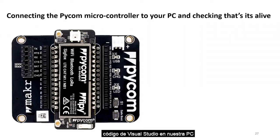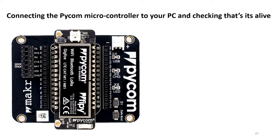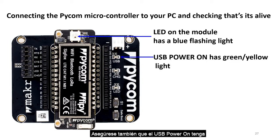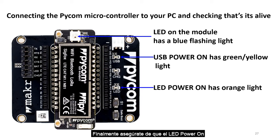Now that we've installed Visual Studio Code into our PC and we've installed Pymakr plugin into Visual Studio Code, we'll go ahead and connect the microcontroller to our PC. And to do this, we need the cable, that is a USB-A to micro USB cable. So go ahead and connect the microcontroller to your PC. Once you've connected your microcontroller to the PC, ensure that the LED on the module has a blue flashing light. Also ensure that the USB power on has a green or yellow light. And finally, ensure that the LED power on has an orange light.